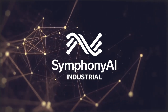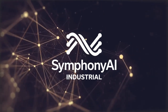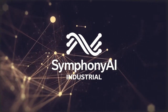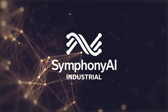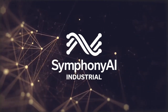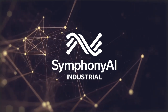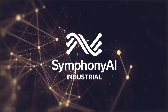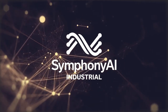And the second biggest advantage is that it is adaptive. So AI models could be very adaptive. They could learn from the changing process and incoming data and keep up to date. And with MPC controllers, you tune them one time, you make a DOE and all the step changes, and it works well for 3 months, and then after that starts deviating. So many times we have seen customers stop using MPCs after a few months. And so AI-based models have some edge there, where they can update themselves and become better as they go.